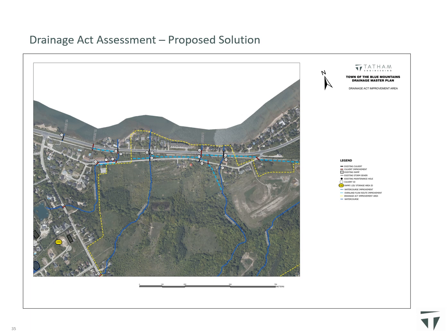The proposed drainage solution involves improvements to existing municipal drains. Watercourse 7 in the study area is the Blue Mountain outlet drain. Outlet 8 is the Blue Mountain diversion drain, and watercourse 9 in the study area is the Ford outlet drain. The proposed drainage solution includes the following works. An overflow channel will be constructed between the Georgian Trail and Lakeshore Road East to convey flow exceeding the capacity of watercourse 9 from watercourse 9 to outlet 8.